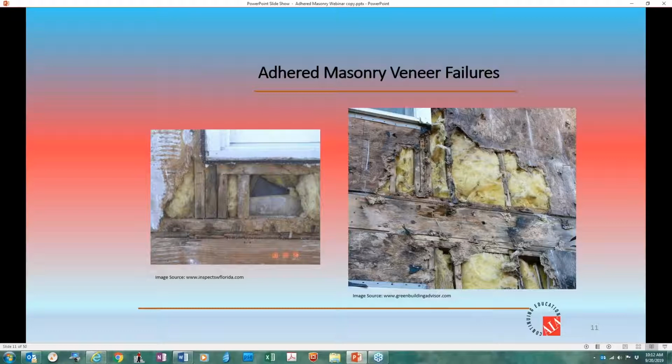Both mesh products will prohibit mortar from entering the drainage base and yet allow for full encapsulation of mortar surrounding the wire lath. The ability for the air, vapor, and water to move basically unrestricted behind the scratch coat was clearly shown in the video. The benefit to the substrate walls is simple. The moisture is going to move behind the scratch coat, in between the scratch coat and the substrate, much faster, with less time for direct contact, which means less time for it to find the voids to enter your wall and create these types of situations.